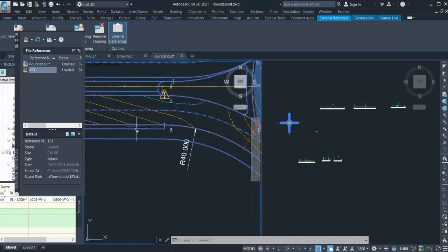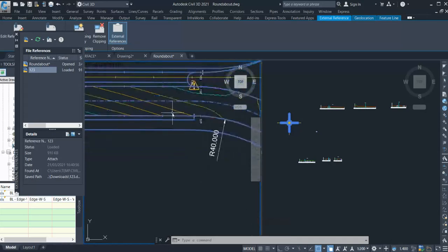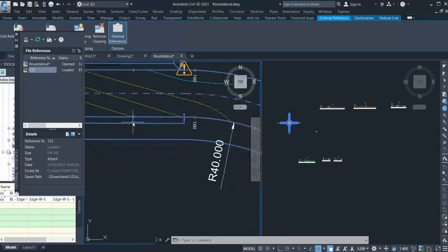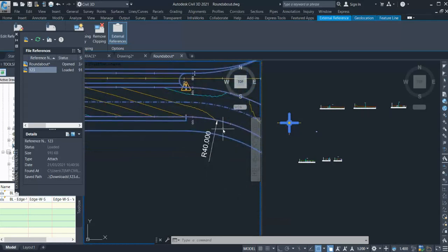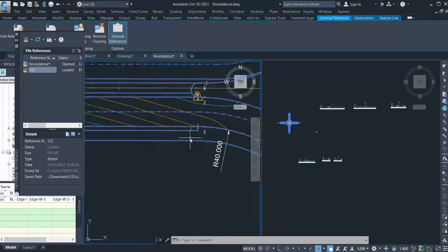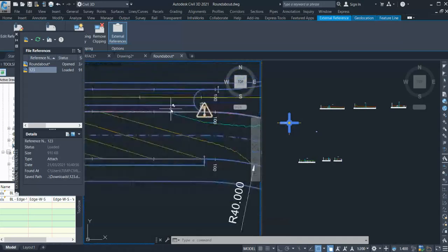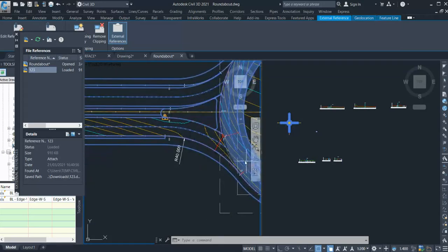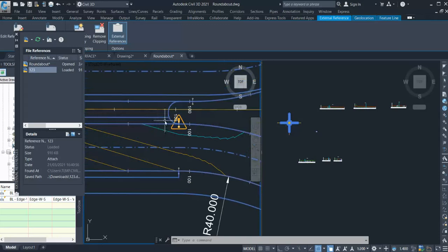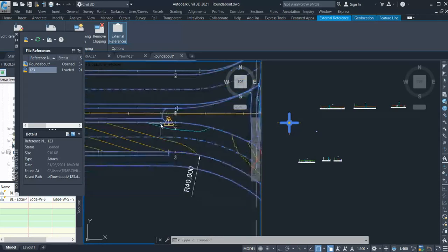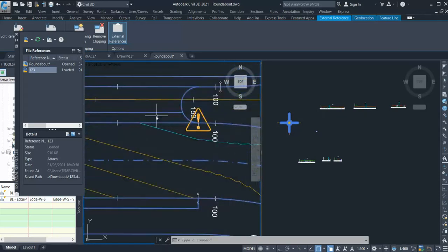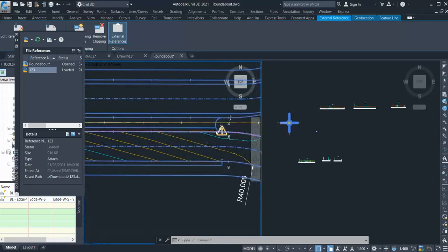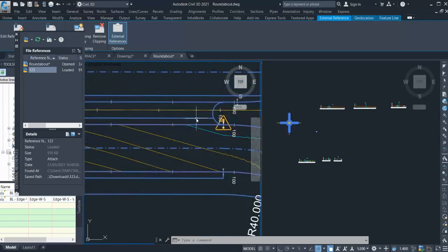That is why I cannot make the alignment go here and then go here and then again. Instead of that, I created a continuous alignment for this. Now for this part, I have to add extra assemblies. Similarly here in the roundabout, on exit, you have to stop the harsh strip earlier. So you have to design this again in different ways. I have not designed those alignments because you have to stop here, then go again, then create again. That would not work, so you have to create another way to design those.